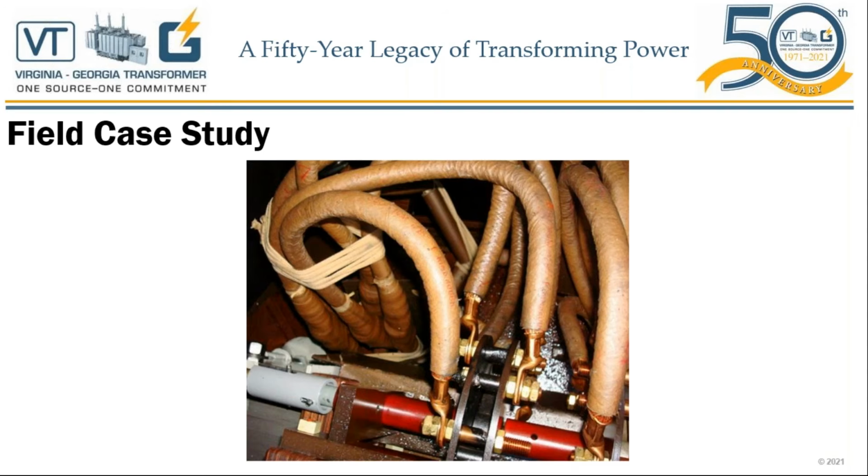This is a de-energized tap changer. As you know, de-energized tap changers generally are on the high voltage windings, and the name de-energized is because they are supposed to be operated only when the transformer is de-energized. However, the failure that you're seeing, the arcing between the two studs there, is not because anybody tried to turn it when it was energized. Before that though, let me explain the de-energized tap changer, how it's really designed.